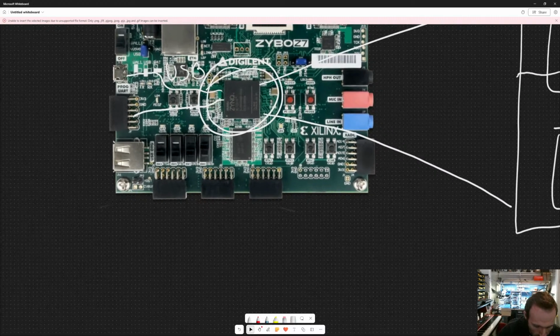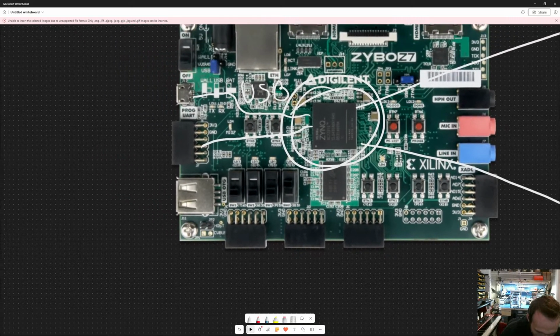And what I was doing prior, the reason why it was not working the last stream is because MOSI and MISO were routed to these pins, but I was measuring these two pins.